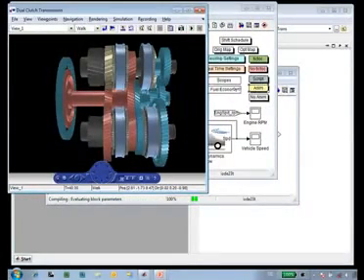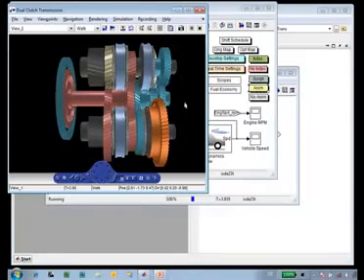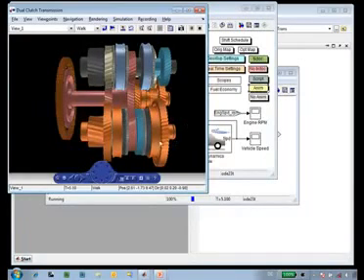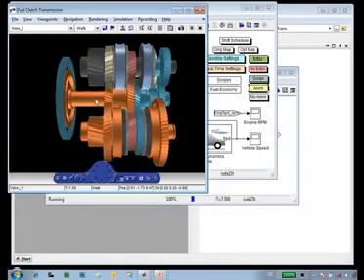So now the entire Sim Driveline model, which models the dual clutch transmission plus the control system and the vehicle dynamics, is running, and the results of that simulation are being used to drive this animation in real time. So this is a live animation. You can see that just as in the test rig, the gears are switching as we explained. Again, the dog clutch pre-selects the next gear to which the transmission will shift, and then the clutches change state in order to actually change gear.